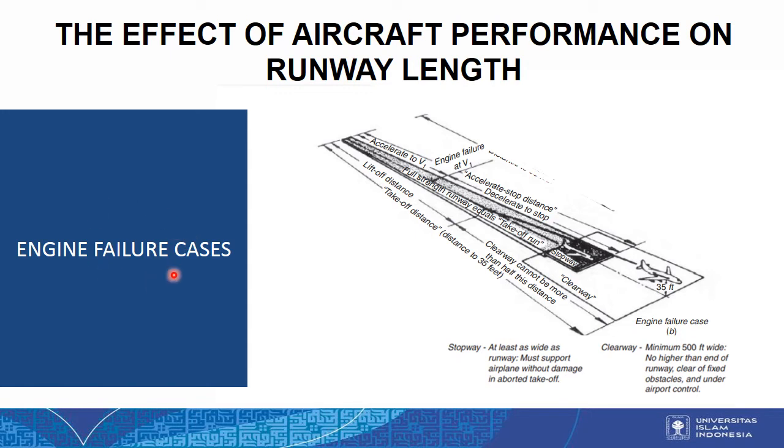The second case is the engine failure case. The engine failure case is described as the case where one engine fails at a critical point during an aircraft takeoff roll and the pilot makes an immediate judgmental decision whether to continue with the takeoff or perform an emergency stop.